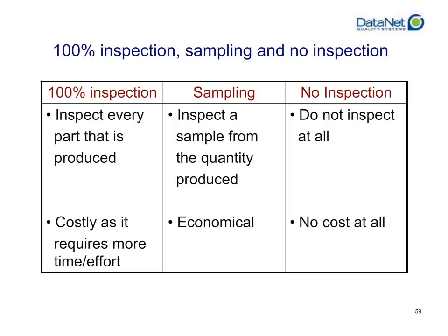It weeds out a lot of the natural variation, and it allows you to focus on just the parts that are shifting, assuming that you track this information properly. Very important to realize there's different ways you could handle it, but sampling for SPC purposes is the way to go and the way to gain the most value.